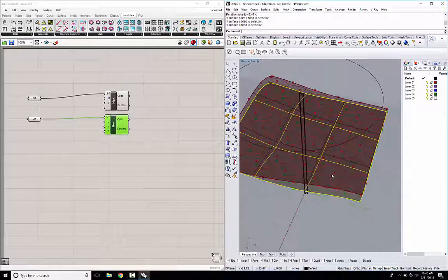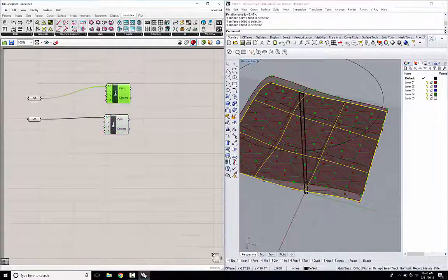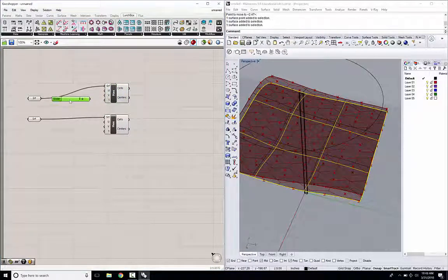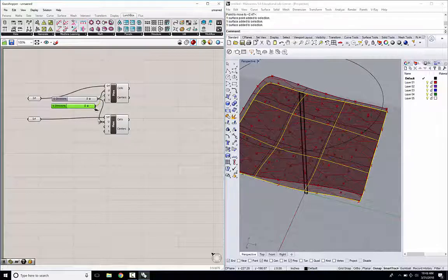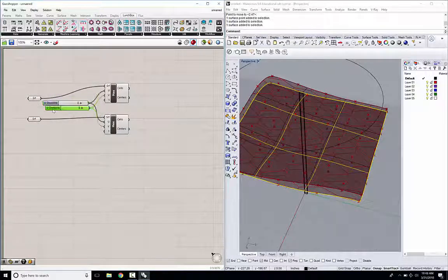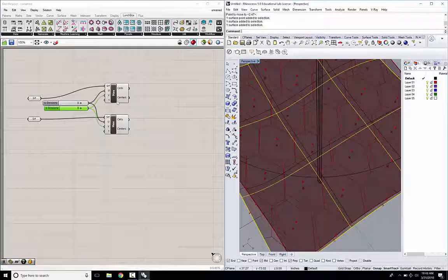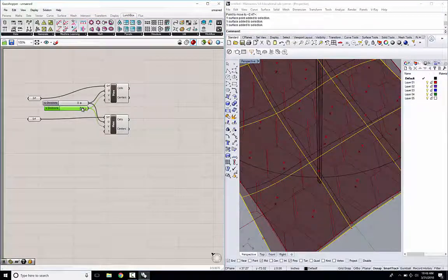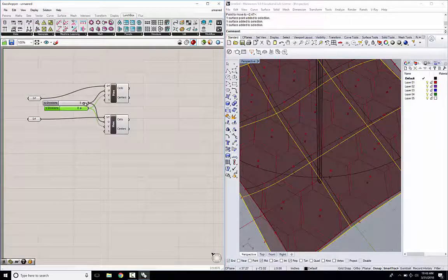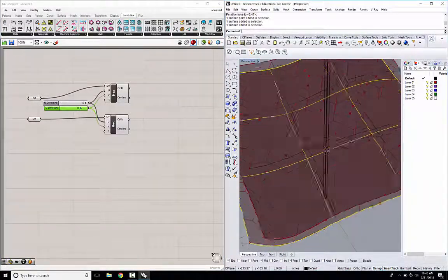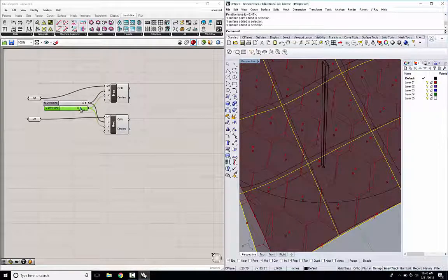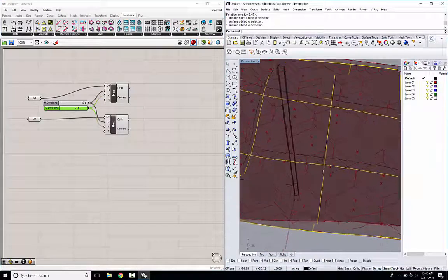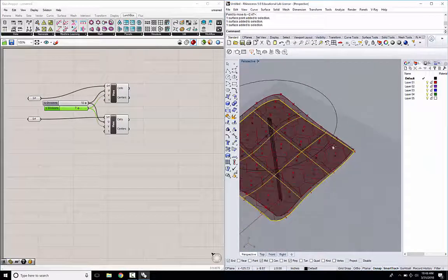And the size of these looks roughly approximate right now. We'll eventually come back and set these. I'm just going to move them to 8s. They have to remain exactly the same. So I'm going to put both sliders into the U's and V's components for each, so that if I do change them, they change equally. So here it looks like, now that I'm at 8, that to get them more evenly shaped, I'm going to have maybe like a 10 by 7. The sides are approximately the same there.